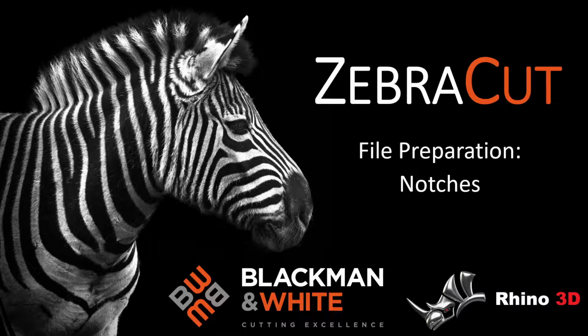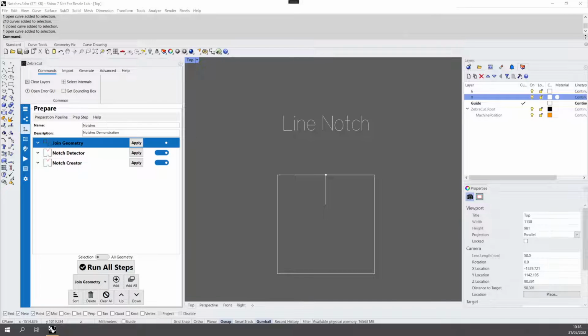In this video we are going to explore notches within ZebraCut, how to detect them and how to place them. So first of all, what is a notch? Well, a notch is a pen mark or a cut mark which is used to help align pieces during manufacturing.